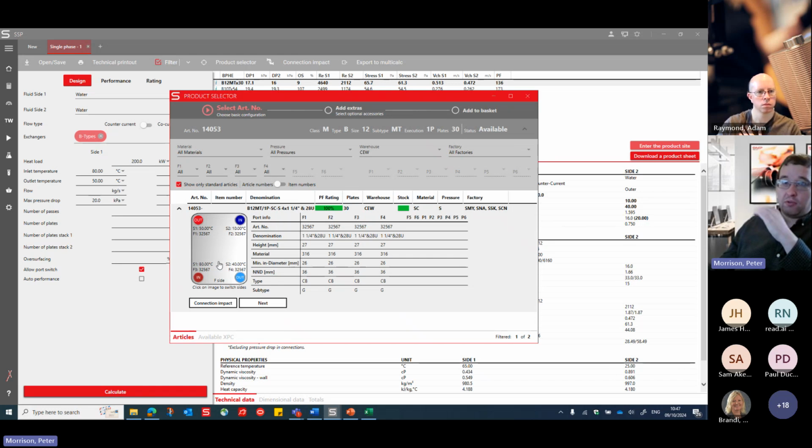One thing I'm going to mention as well, just because we do get asked this quite a lot. It's saying here you should be hot in this side, hot out here, cold in here, cold out here. A lot of people will ask, is it possible to move these around? The answer is yes. This is a recommendation, provided that the inlets are diagonally opposite each other, in which case the outs would also be diagonally opposite.